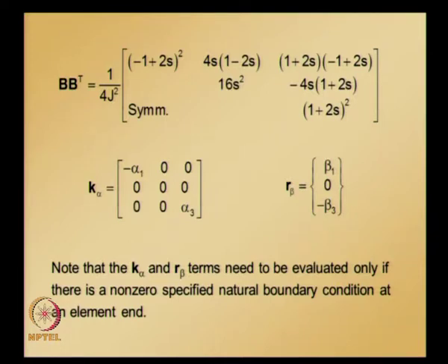So, we will solve the same problem now using quadratic element. If you recall, when we discretized the domain using 4 linear elements for the column buckling problem, we noticed that the critical buckling load that we obtained has about 5% error. Now let us see how much improvement we get using this quadratic element for the same number of nodes for the entire domain.